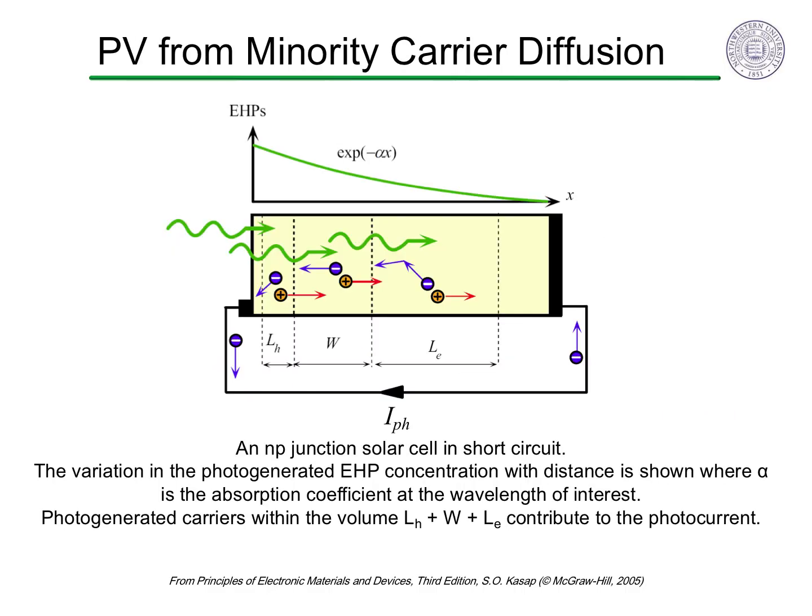In a typical PV, the photocurrent doesn't just come from the electron-hole pairs produced in the depletion region, but also within a minority carrier diffusion length of the junction. The light intensity will generally decay exponentially where the absorption length is a characteristic of the semiconductor. The side facing the light is often an N-type region made so thin that most of the light goes through the space charge region quickly.